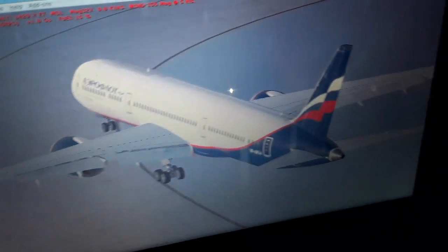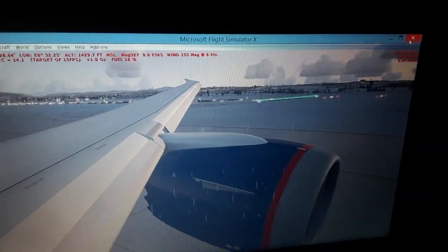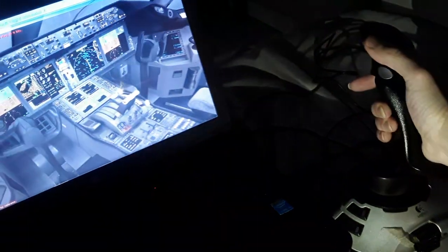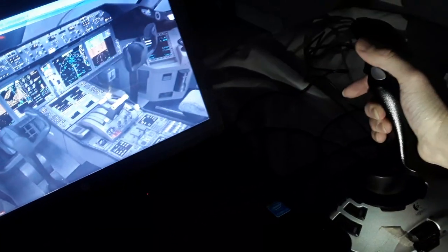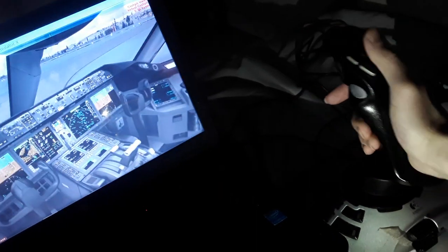So this kind of control. So it's side stick left and right, the rolling axis, the longitudinal axis of the aircraft, to make bank rolls in flight left and right. You can use all flight controls together. So you make bank rolls with the control wheel. Like this is the side stick in the Airbus, and the control wheel on the Boeing, to make left and right turns. So the elevator, climb, descent.